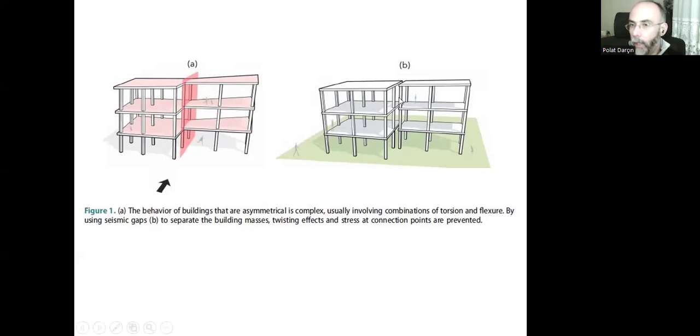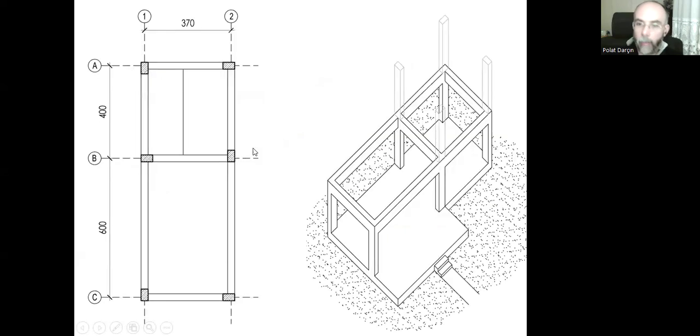That's a complete gap, there is no connection at all. Nothing is connected. And we construct the other building, a neighbor building. With the covering pieces that close the gap, the users cannot understand that they are in two separate buildings. They think they are in one building because of the small size of the gap.